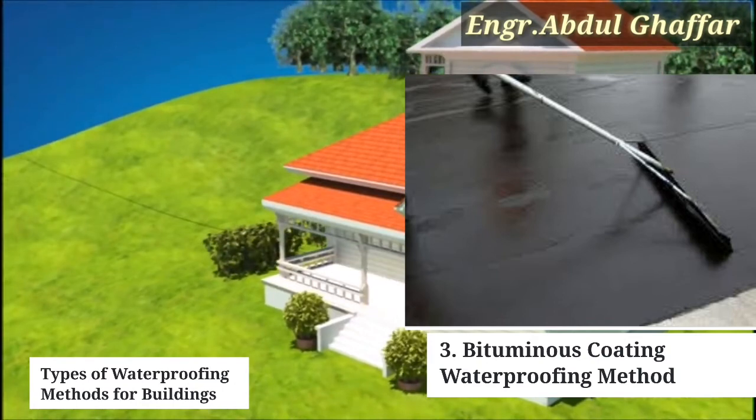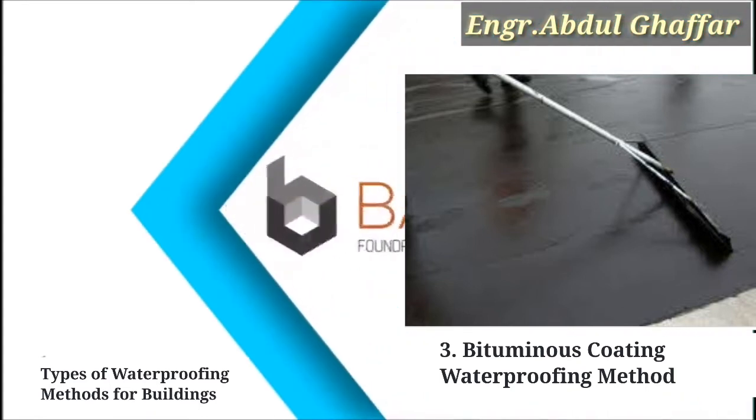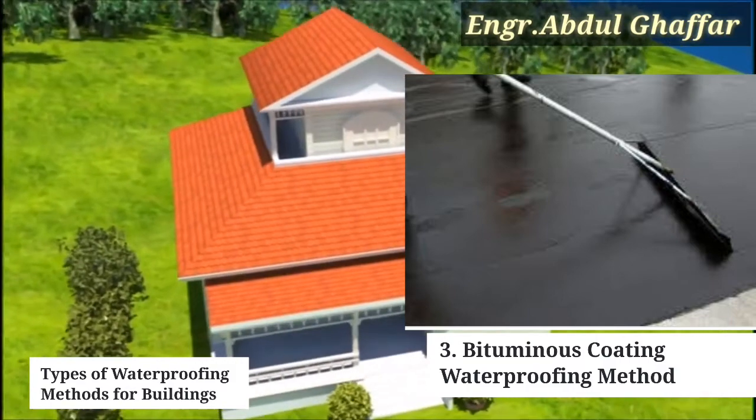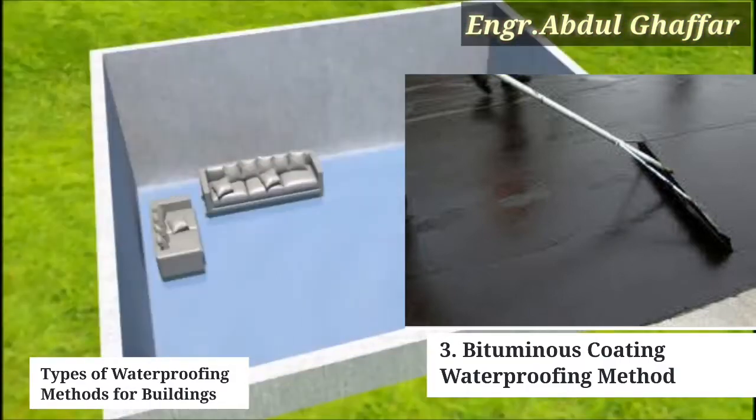The most common applications of bituminous coatings include areas that are beneath screed bed. It is an excellent protective coating and waterproofing agent, especially on surfaces such as concrete foundations. Bituminous coating is made up of bitumen-based materials, and it is not suitable for exposure to sunlight.